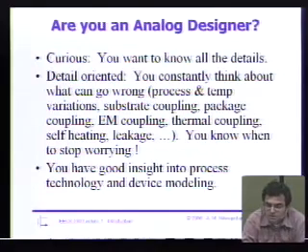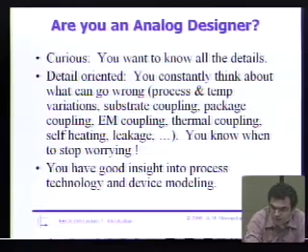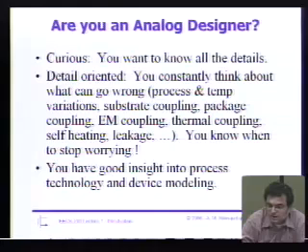And if you design a circuit and it works in your lab and your customer puts it in his or her circuit and it doesn't work, boy, you're in trouble. You're going to have to spend all your time understanding why it didn't work in a different environment. Other things that aren't really in your model: thermal coupling, self-heating in the transistor, leakage mechanisms, extra leakage mechanisms, proper conservation of charge.